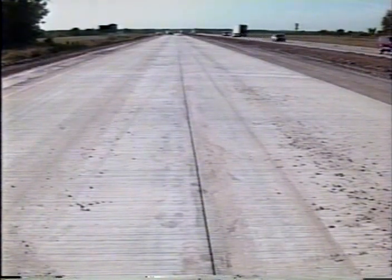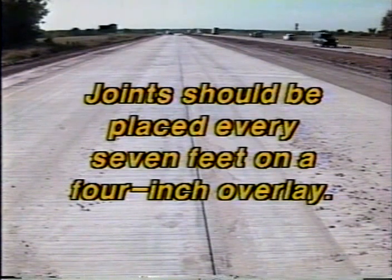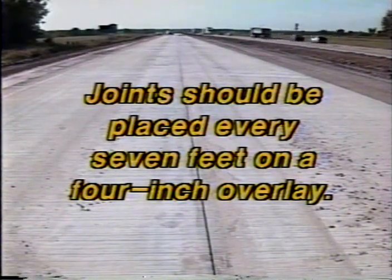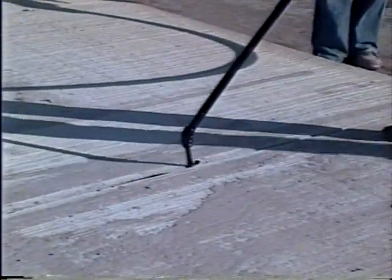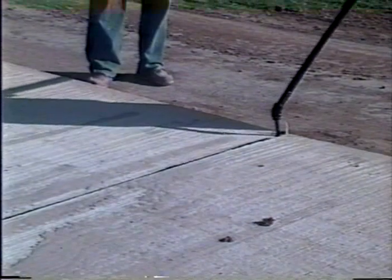For example, joints should be placed every 7 feet on a 4-inch overlay. The joints in unbonded concrete overlays should be sealed using the same procedure and materials used for new pavements.